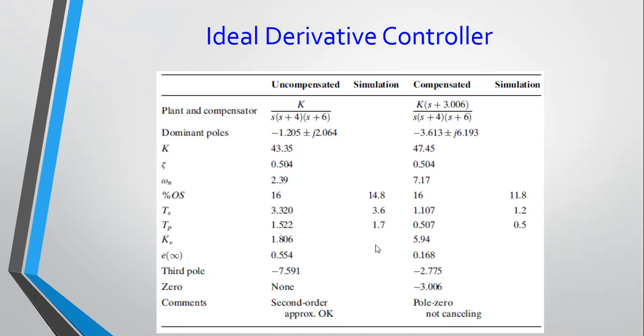Okay. And you can find as a result peak time has also reduced. As expected here, if you find your operating point to be this one here, you can see your imaginary part has also been increased here. So you expect your peak time to also reduce. So this is our PD controller design with your specifications to do with your settling time, peak time, or any of the transient parameters. You can use them now to calculate a new operating point. From that new operating point, you can find what angle your PD compensator needs to provide, and from there you can just locate your 0. That's more or less what you do in PD control design.